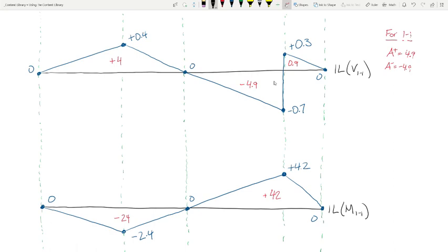Where should I put the distributed load for worst case positive shear? So we'll call this V max positive. Where should I put the distributed load? A to B and D to E. What about B to C? A to C, sorry. Put it from A to C? Well, what about right here? That's only 0.9. But it's positive. Everywhere that would generate a positive shear is where I'm going to put that load. I propose that I need to put that load right here.